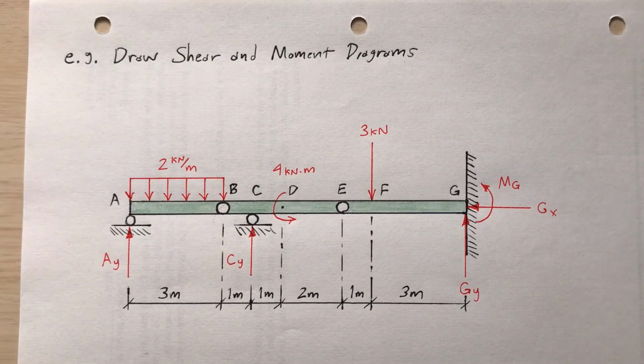At B and E, you have hinges. So the first thing I should probably do is calculate what the external reactions are. I don't think I can do it based upon the equations of equilibrium. There's too many unknowns. So I'm going to dismantle this. I'm going to unbolt it at hinge B, and I'll analyze segment AB first.